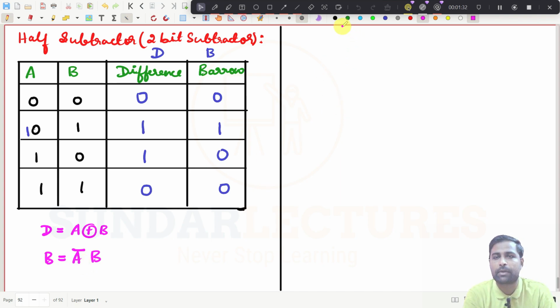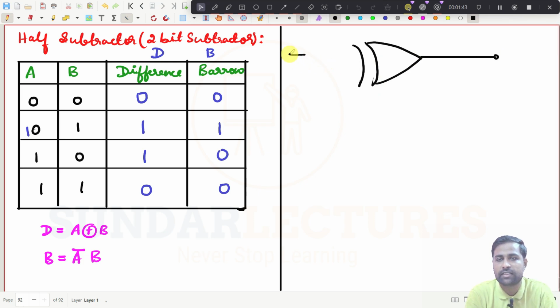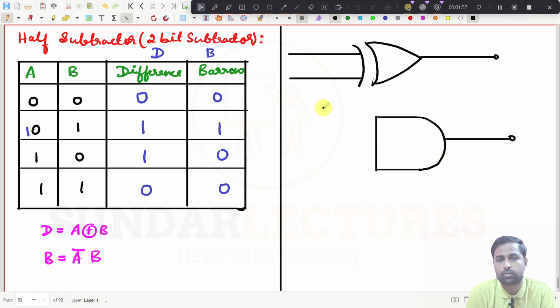So what should be the diagram now? I will go fast now because we have seen everything in the previous one, right? In the half adder, whatever you have done, the same thing is existing here too. That is why I'm just going very fast. So this one, and then I should have an AND gate here. So I will draw it down. Maybe see this is now A, this is now A, and this is now B. And I am taking this one to be difference, and that should be equal to A XOR of B. Simply, I have got the answer.